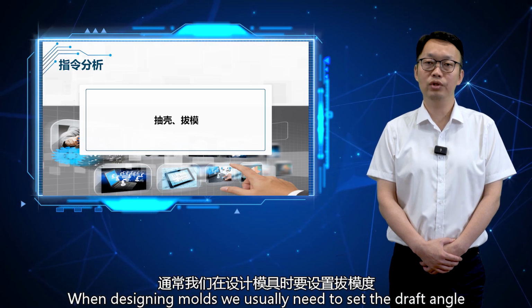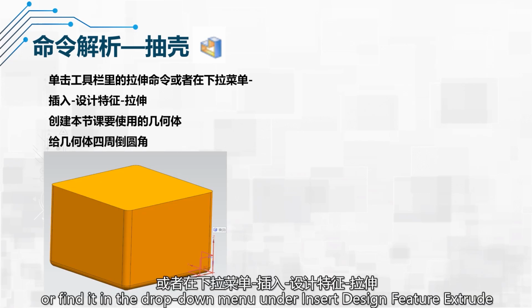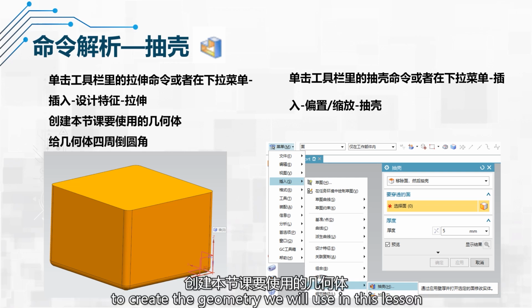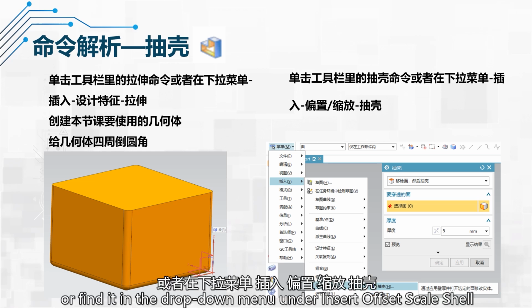When designing molds, we usually need to set the draft angle. Click the Extrude command in the toolbar or find it in the drop-down menu under Insert, Design Feature, Extrude to create the geometry we will use in this lesson and add fillets around the geometry. Click the Shell command in the toolbar or find it in the drop-down menu under Insert, Offset or Scale, Shell.